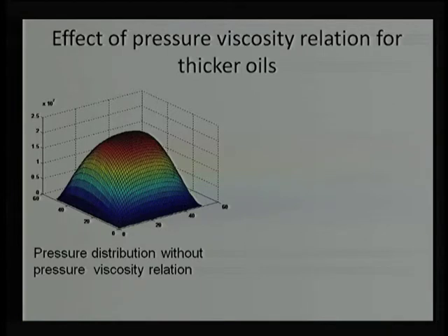However, there is a point to see if viscosity increases, or if we are thickening the oil. When we go for the thicker oil, we are able to see the pressure increasing in magnitude. In the earlier case, the previous slide, it was 7 into 10 to 5. Now, in this case, we have increased viscosity by 20 times. Earlier it was 10 millipascal second, here we are considering 200 millipascal second, and the viscosity of the lubricant has been increased by 20 times. The base oil viscosity itself is increased by 20 times.